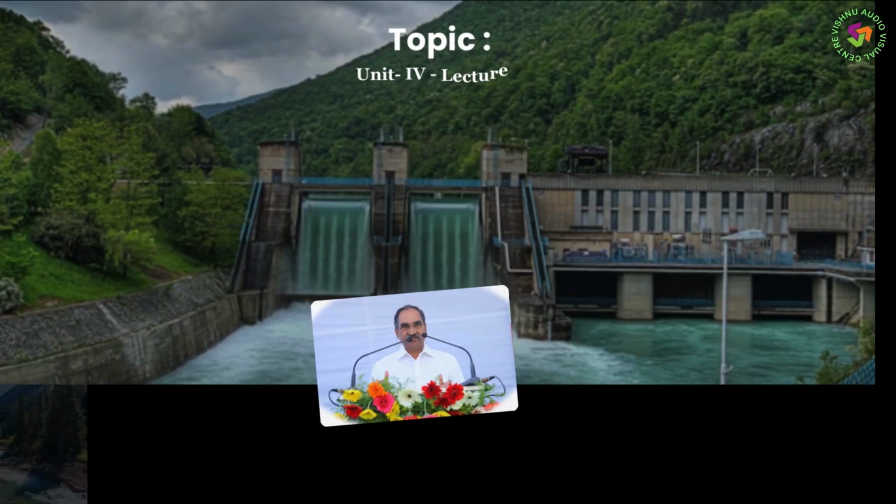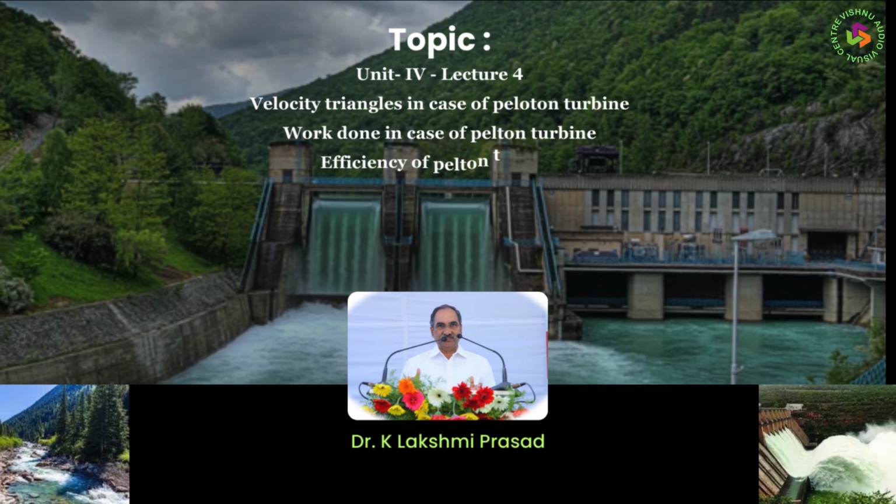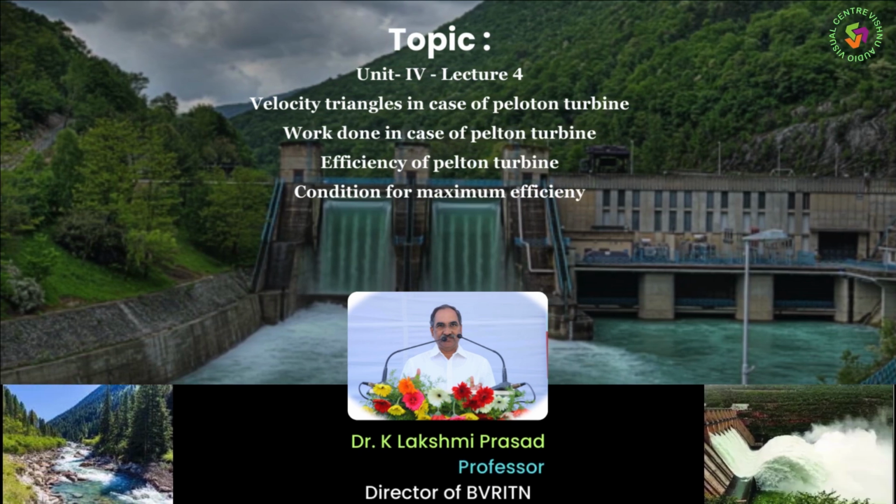our aim. So here, in the case of a tangential flow turbine, we first derive the equation for force using the impulse momentum equation and then multiply it by the velocity of the vane so that we get the work done. Whereas in the other case, using the angular momentum principle, we calculate the torque, and from torque we calculate the work done.